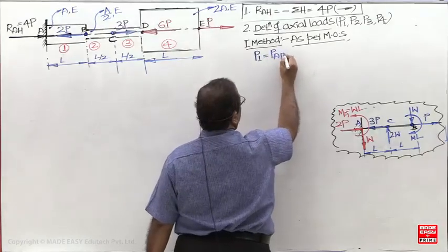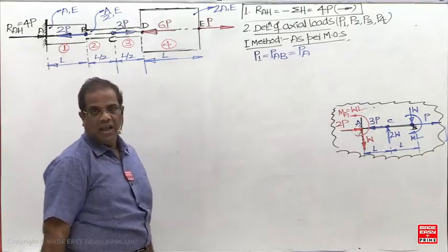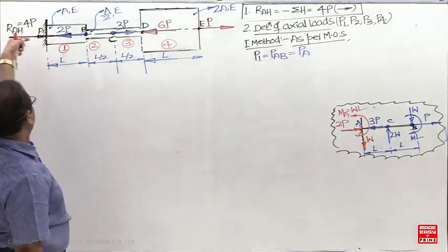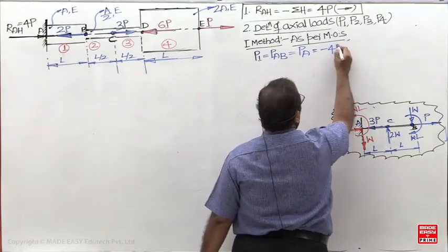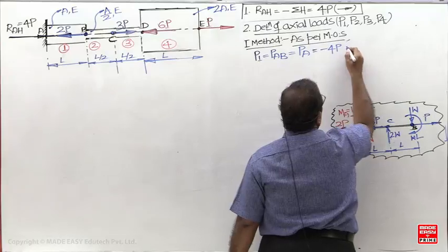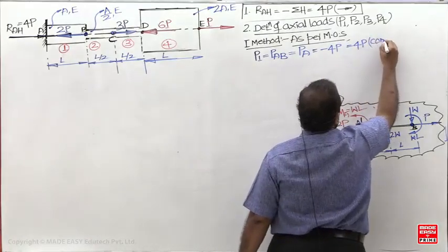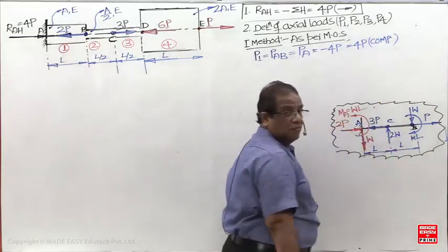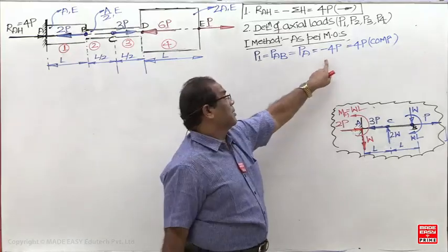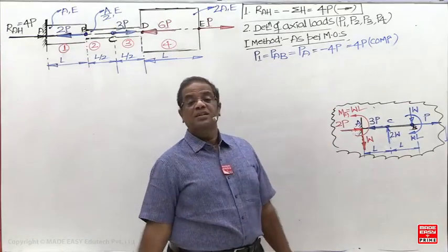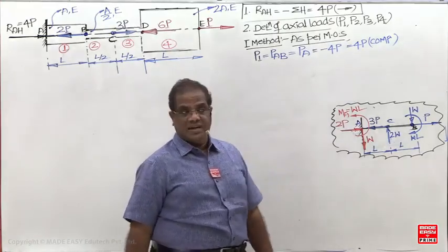For the AB member, which is the non-junction A, directly what is the load at A? 4P compressive. And once again, don't use minus or plus for the bending moment either. Here minus means compressive. For a vertical member, bending moment is positive means sagging, top surface gets contracted.